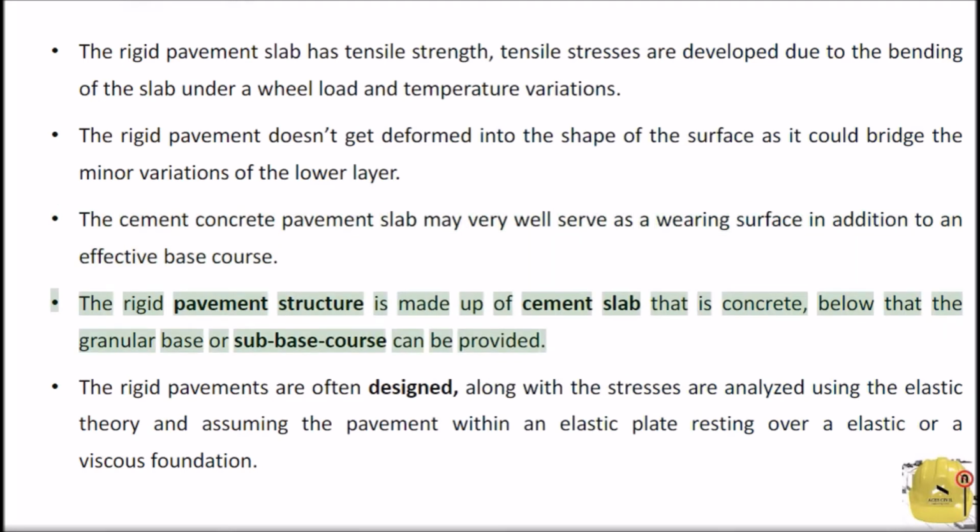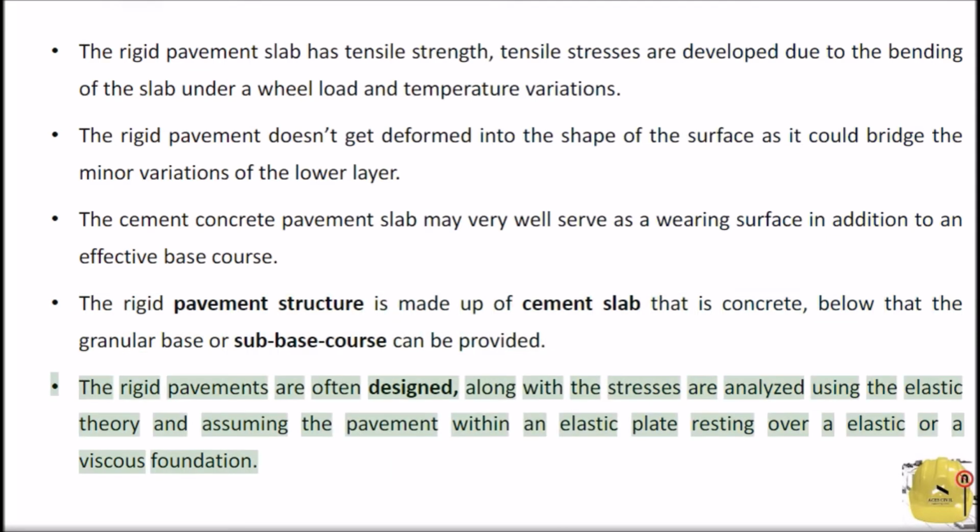The rigid pavement structure is made up of a cement slab, that is concrete. Below that, a granular base or sub-base course can be provided. Rigid pavements are often designed, and the stresses analyzed, using the elastic theory, assuming the pavement to be an elastic plate resting over an elastic or a viscous foundation.